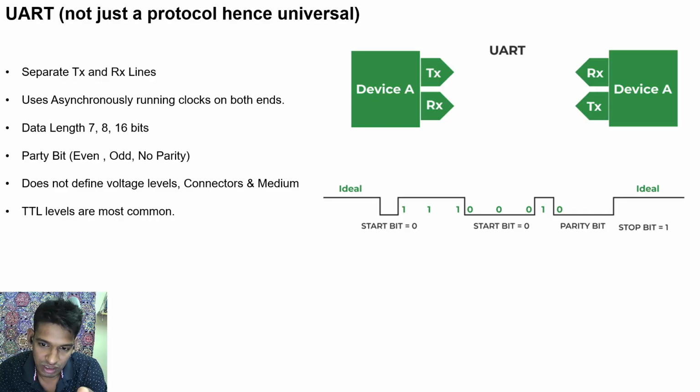And suppose you're counting the number of ones and detecting an odd number, then your receiver understands that, okay, I am using even parity, but I have counted an odd number of ones. That means at least one error has happened. So that is what parity is. Using a parity bit cannot help to resolve the error, but it can help to identify the error.